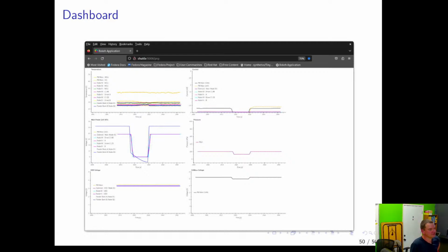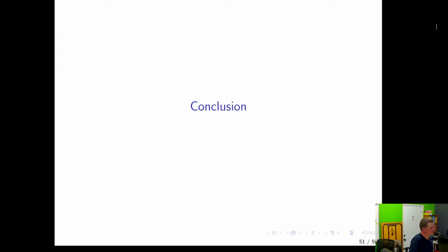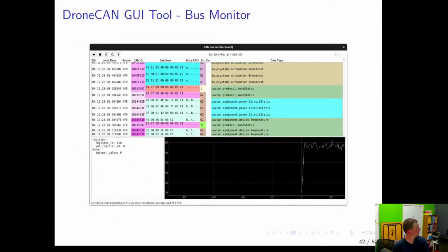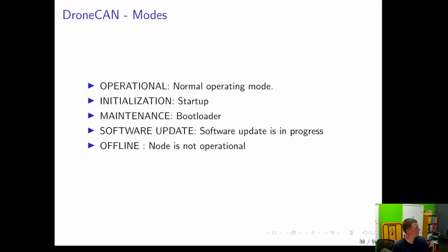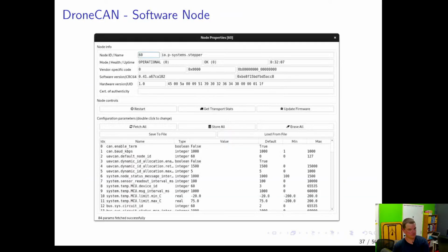So back in the socket example, in the socket example you have some code to respond to a frame, but how does that work when you have something that is like a subframe that you have to twiddle? Like you have to twiddle the ACK bit, right? Oh, the controller will do that for you. So the stuffing, you're talking about the stuffing bit or the ACK bit? Not the stuffing, but the ACK bit.